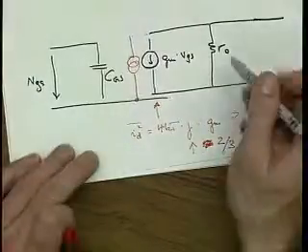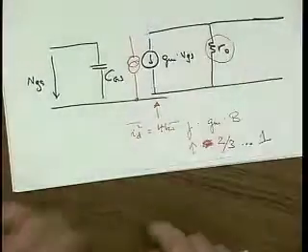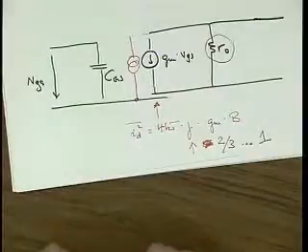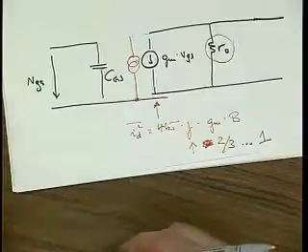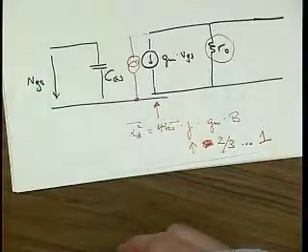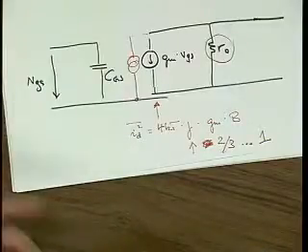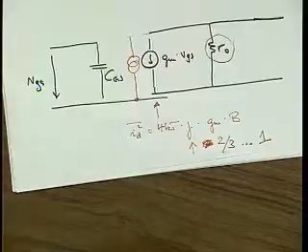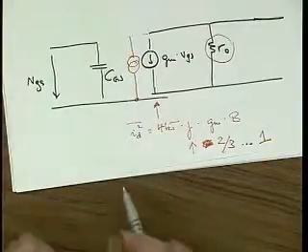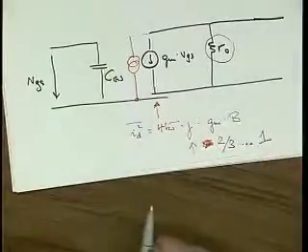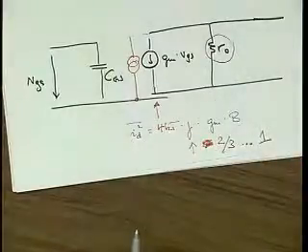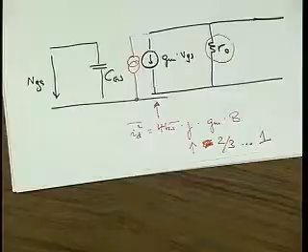What about this resistor here? Does it have thermal noise? Well, it doesn't have thermal noise because there isn't really a dissipation mechanism associated with it. That's only this effect that the amount of current that flows in our transistor varies a little bit as a function of VDS. This is really only a modeling resistor, and as such, it doesn't have noise. Okay, thank you. I take that.